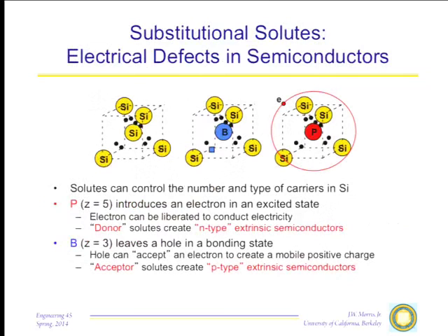The most important and obvious place where we see the effect of point defects is in the electrical properties of semiconductors. I mentioned this last time. If we take silicon, for example, which has 4 neighbors, 4 electrons, so the bonds are saturated. If we replace the silicon by boron, we have too few valence electrons, so there is a hole in the valence shell. This hole is weakly bonded to the boron, can be shaken loose, or if you want, an electron can move in and occupy that position. Then the hole, which behaves as a positive conductor, can run through the lattice and conduct electricity. If we use a defect that has too many electrons, like phosphorus, we get an extra electron weakly bound to the phosphorus. It gets shaken loose and can conduct by means of electrons.